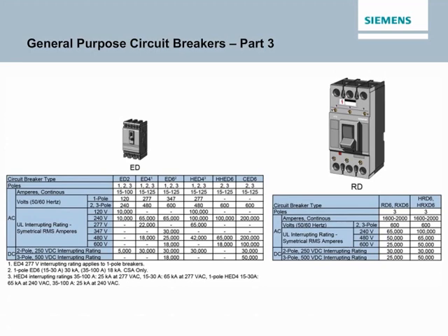Where the type designation includes an X or has a C prefix, the breakers are designated as a complete breaker assembled without lugs, indicating that the breaker has been assembled with a non-interchangeable trip unit and lugs must be ordered separately. All circuit breakers with the X designation, such as JXD2 and JXD6 breakers, are UL listed for reverse feed applications. This means that power can be applied to the load side of the circuit breaker. Selected circuit breakers are available as an instantaneous magnetic trip circuit breaker for use in motor circuits where motor overload protection is provided separately. Additionally, a few types are available as a molded case switch.